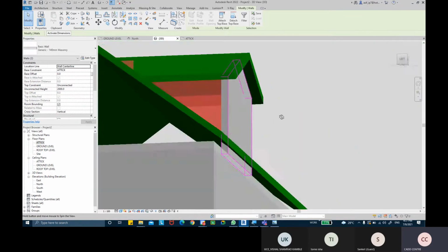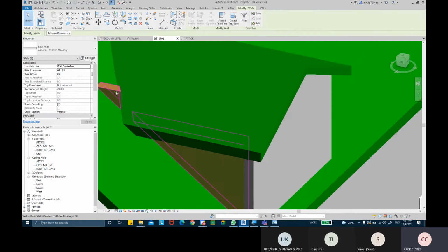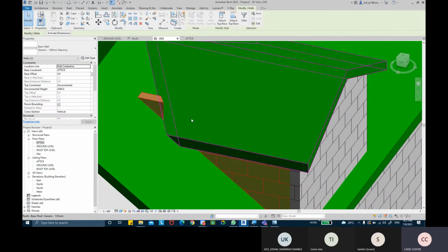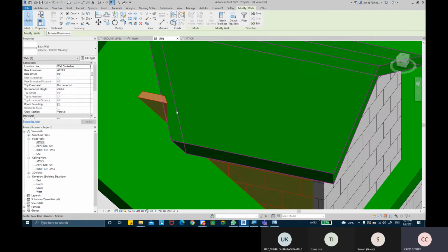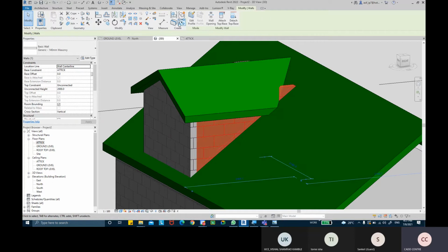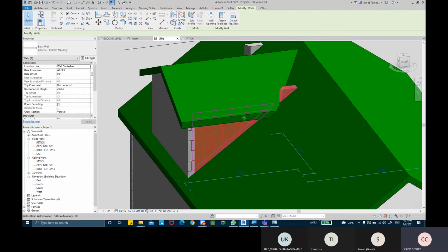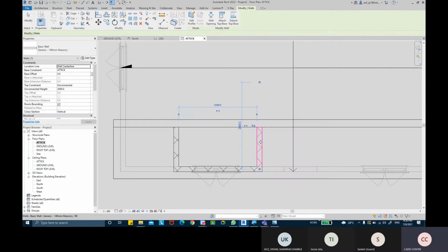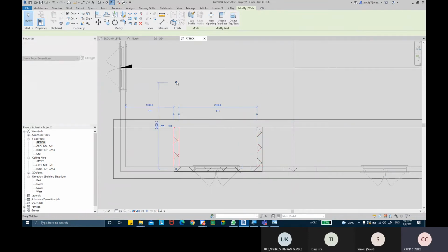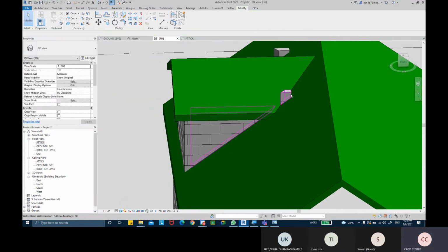Okay. Now you see that wall is not even coming inside that part. Now somewhere over here this wall is overshooting it basically. Same over here as well. So we can once again select and use Attach Top/Base. It's already attached, but it's slightly extended, so this wall needs to be slightly reduced. So once again I can come to the attic level, select this wall and push it slightly back. Still needs to come back.